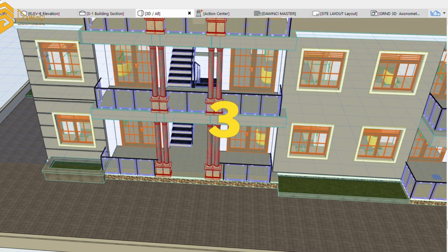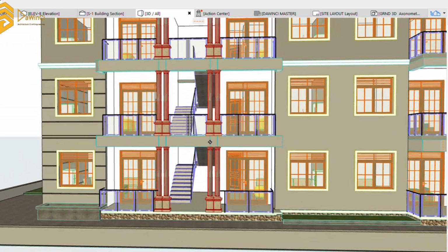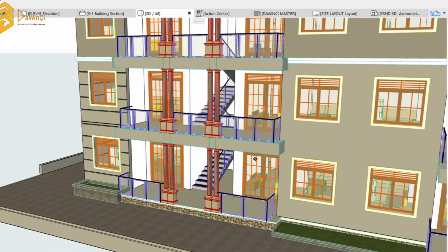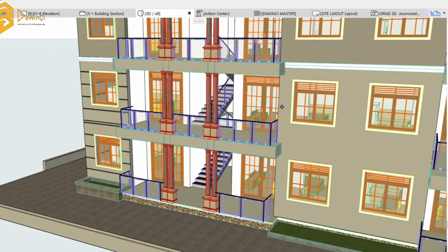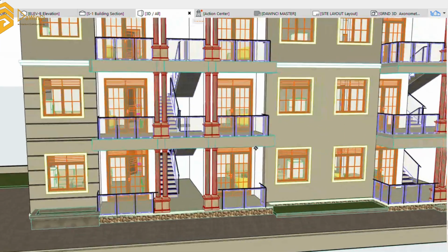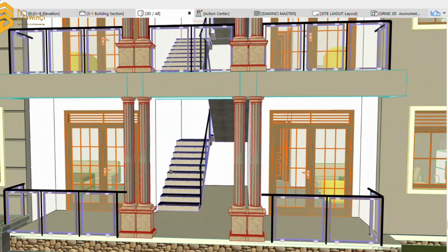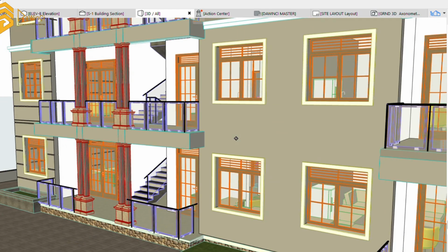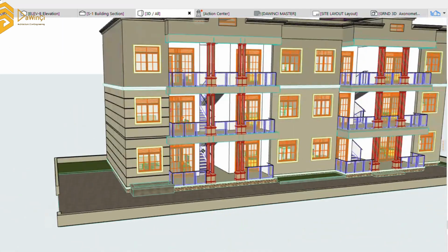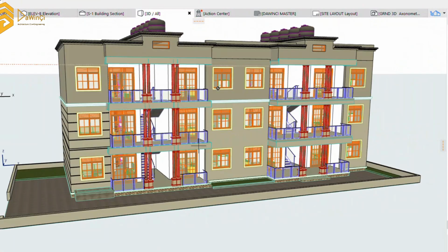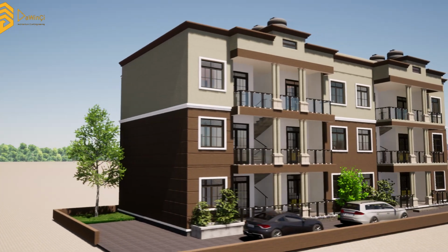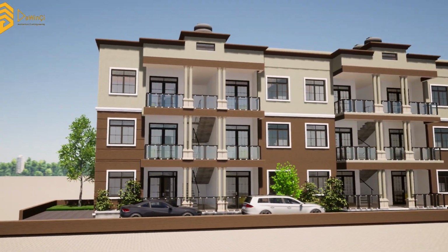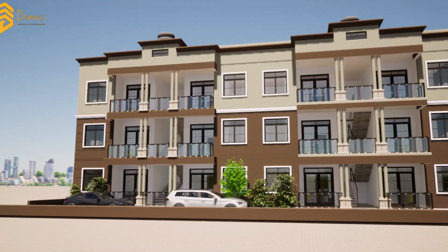So going to this criteria, or this sample of a design, one of the ways in which we can have single bedroom apartments on a 50 by 100 plot, already as a starter you can see that with this kind of arrangement you literally have no parking. You just have cars lining here, but it's still not enough space really. It might cause a lot of squeezing, and of course, even though you can have an extra parking slot here, that would not help a lot. Anyway, this depends on what kind of people you are targeting as a landlord, okay?